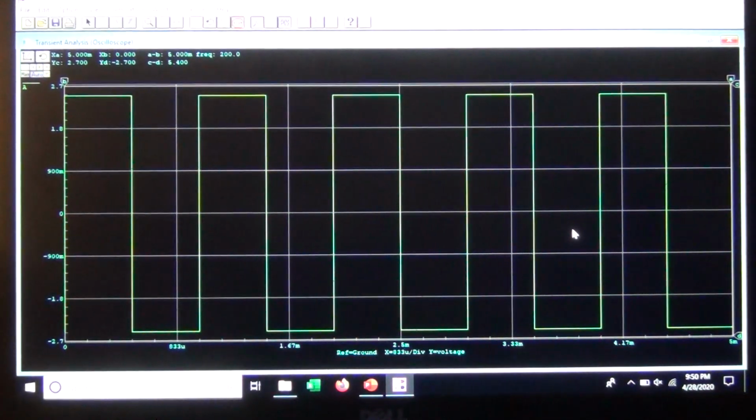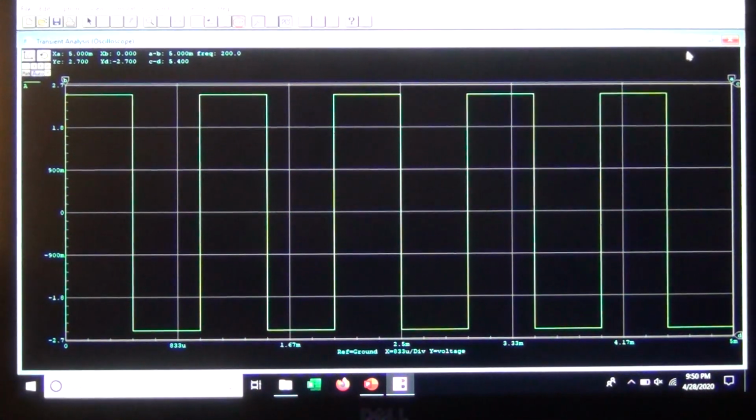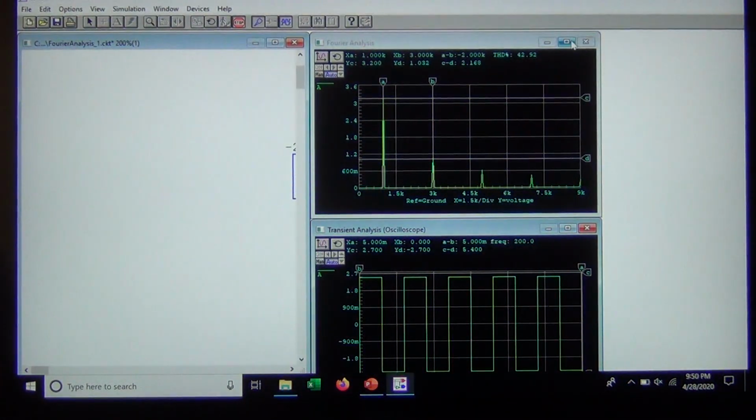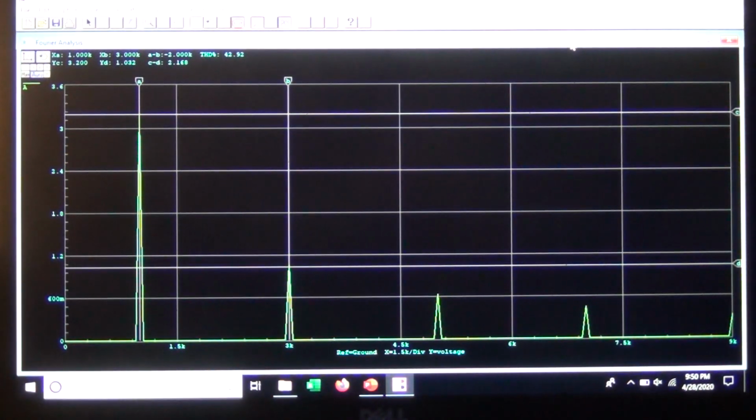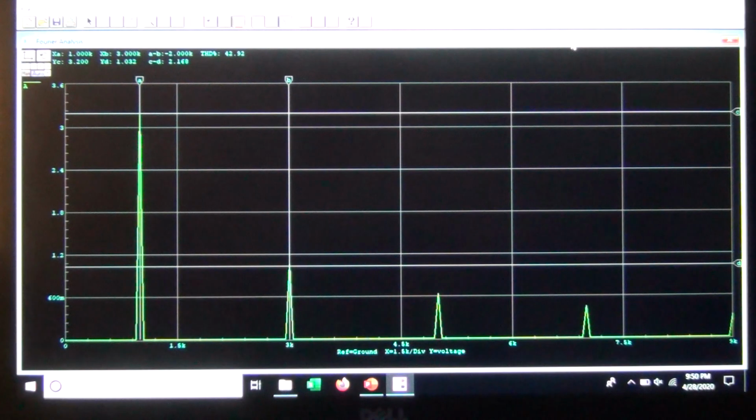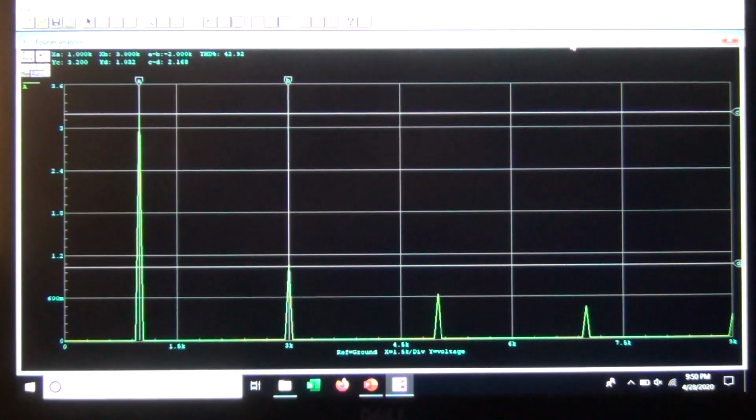Well, this would be the basis of a mechanical oscillator. It turns out the physical action of throwing a switch back and forth like a metronome to produce a signal would actually produce these new frequencies that you see in the Fourier analysis. In your life experience, you may be aware that when we have a thunderstorm, you have lightning, and lightning is a little bit different. It's like an impulse, and it turns out that an impulse generates all frequencies whose amplitude goes down by 1 over f, actually. And we could use a Fourier transform to predict that.